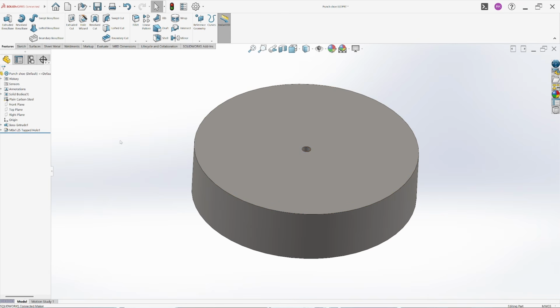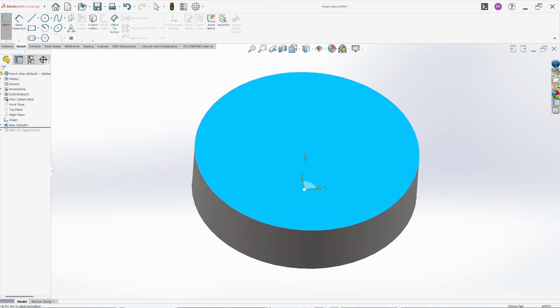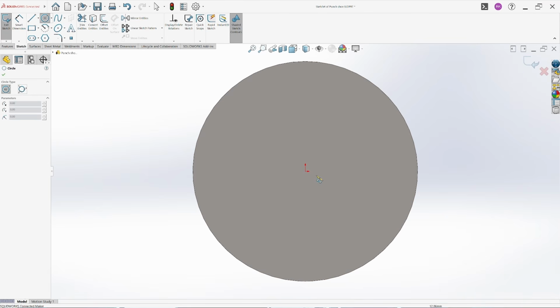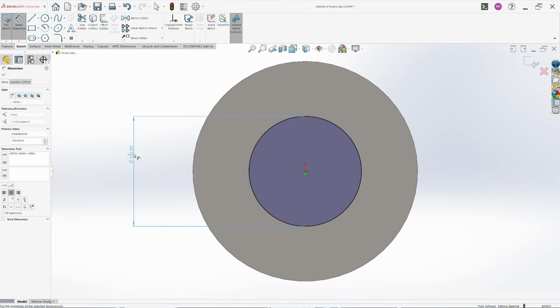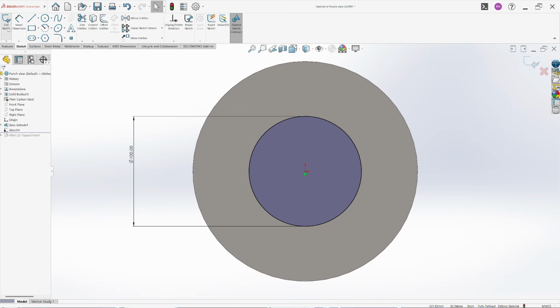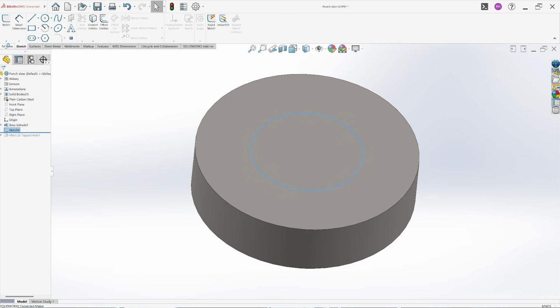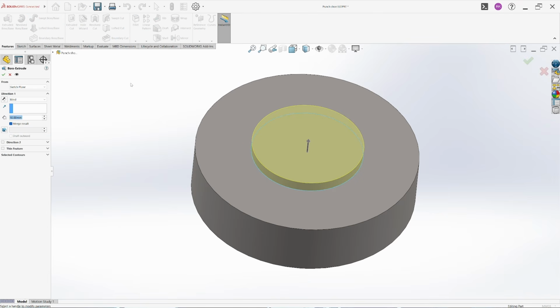But I made this threaded hole first. So what I can do is lift this bar up and make the guiding step right here. Let's say I want a guide step with a diameter of 100 mm. It's a very nice number. Close it and set the height of the guiding step to, let's say, 10 mm or 5 mm, it doesn't really matter, but let's go with 10 mm.